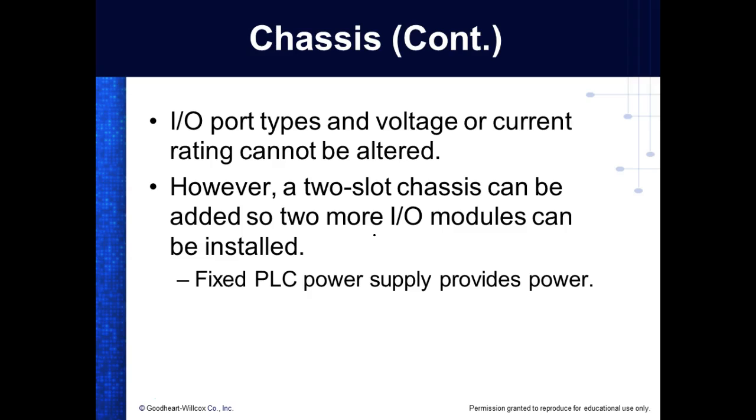You can look up the data sheet on your PLC output module, and it would tell you how much electrical current it could drive. Rule of thumb is about 2 amps. But some of them can drive more, some of them can drive less. So you're not going to run a big motor on a PLC.